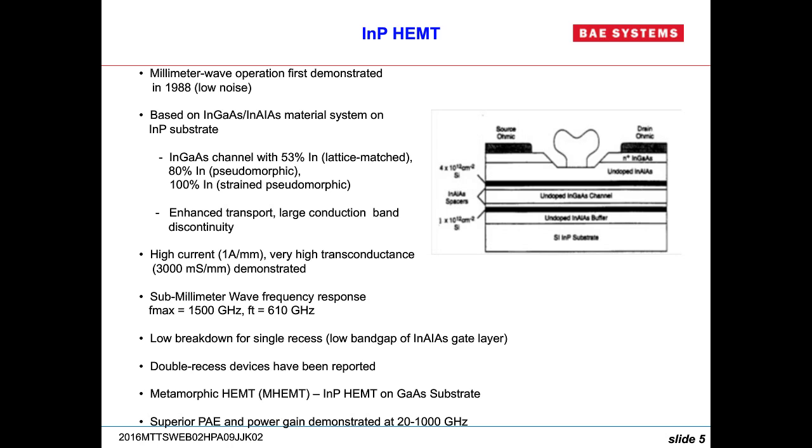My rule of thumb is that you can make a very good amplifier to 1/3 of Fmax, and you still can make an acceptable amplifier to 1/2 of Fmax. So we're pushing terahertz type of performance, true terahertz type of performance with this transistor. The downside is the higher indium, and the structure for indium phosphide HEMT gives you low breakdown voltage, which reduces the power density.